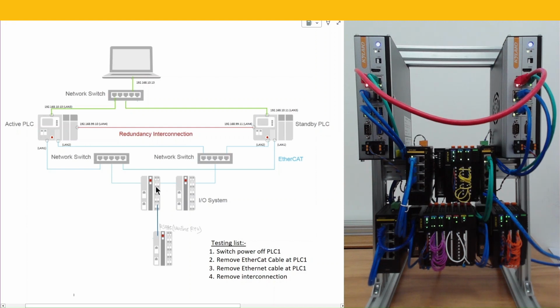So on this EtherCAT, we have the EtherCAT connection, coupler 1 and coupler 2. Notice it's connecting in line topology, with the benefit of this network switch. Let me show you. This is network switch 1, and this is the second network switch, and the line topology is connecting to the first coupler, which is this coupler, followed by this coupler.